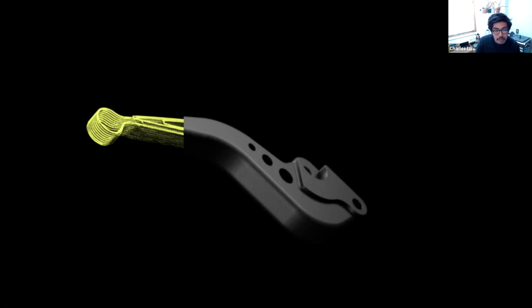Pulling layers apart, with fiber weaker than pure Onyx? Roy's question here. That's a great question. Logically, I think so. It's not like significantly weaker, but it probably is weaker. The Onyx being that it's just more polymer bonding to more polymer. Fibers don't bond to fibers, right? So if you have a material which is more fiber trying to bond with another material with more fiber, you're going to see probably the polymer bond being stronger.